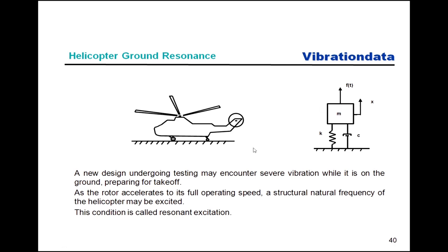The third thing we want is for the pilot to be trained so that if for whatever reason this resonance does start to occur, he pulls back on the yoke quickly in order to get up off the ground. Because once the helicopter is off the ground, the resonant possibility just goes away. So one of those is pilot training, but an ounce of prevention is worth a pound of cure. I would rather design the system so it had enough damping and so that the angular acceleration was quick enough so we mitigate potential resonance effects. So you might think, okay, well, that's nice.